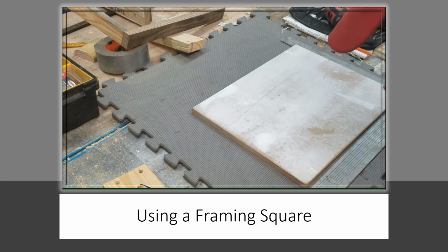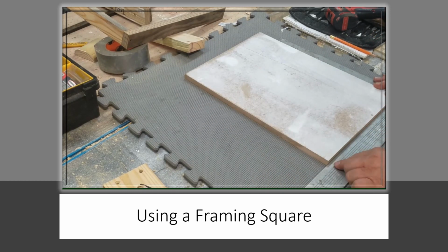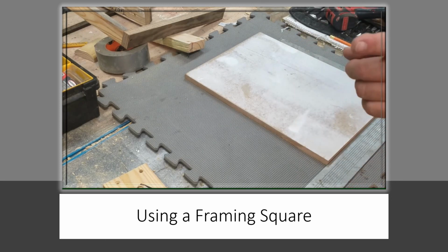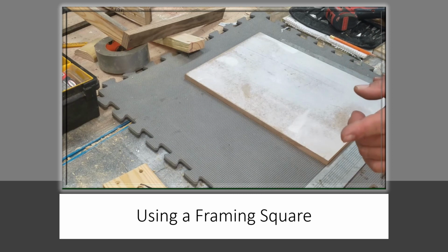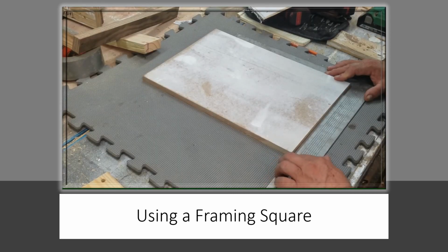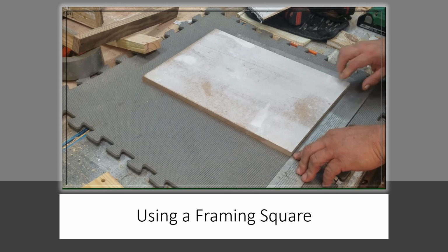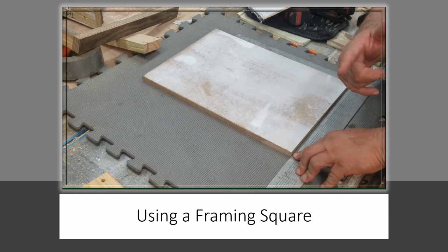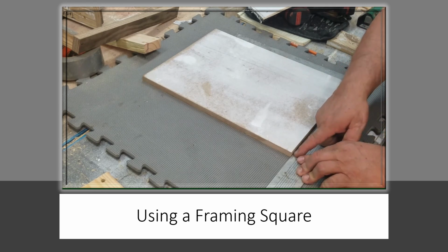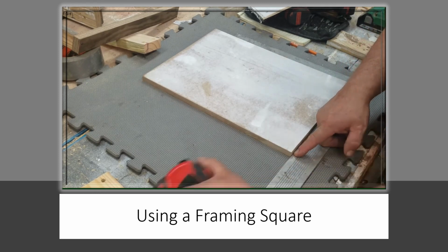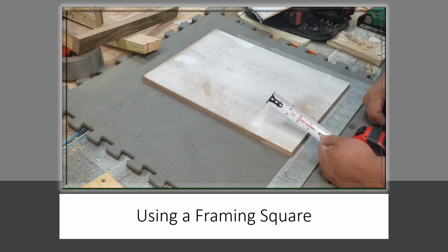Well, if I happen to be, say it was a 16th to make it easy, and the building was 80 feet. If it was a 16th off here, out there it'll be 80 16ths off. If it was a 16th off right here, and we were using our framing square to square up a building 80 feet long, 1/16 here would be 5 inches. That's how far out of square that building would be. They would make you tear it down and start over. That would be just terrible.